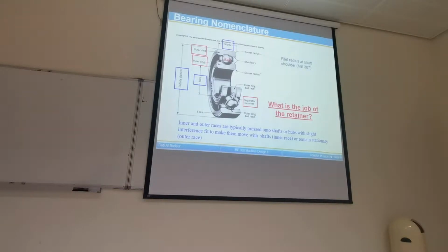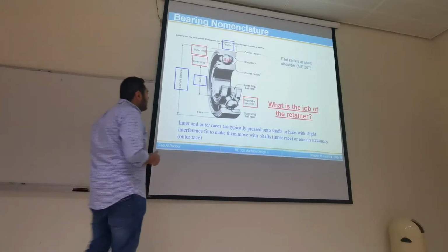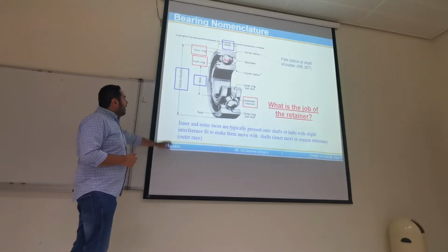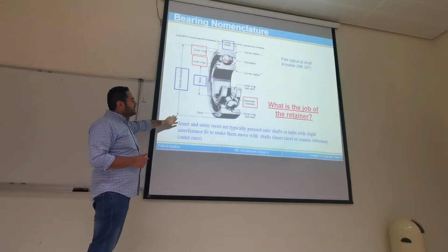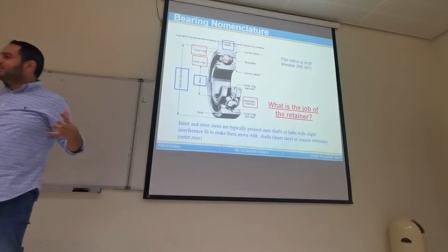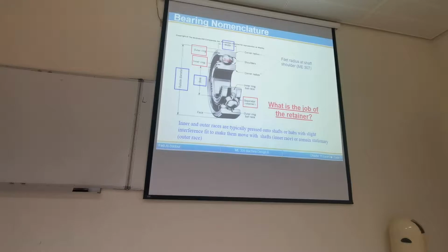If there's a slip, it means there will be friction and heat developed, and wear, between again the shaft and the bearing, in this zone. Then we have the outside diameter. The outside diameter also determines the size of the bearing. So every time the outside diameter increases, it means the rolling element inside is bigger.